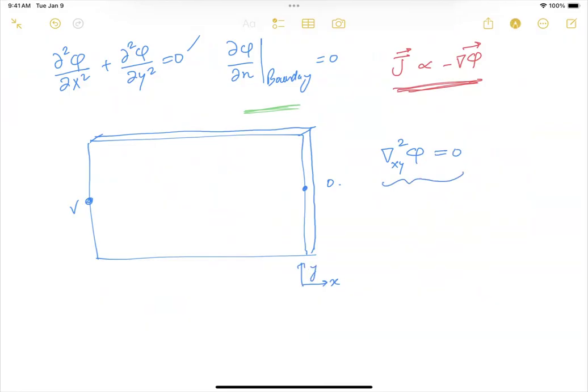And if you look at the form of this mathematical expression, it's very similar to what you would expect as the potential equation for when you have 2 point charges which are located in free space. So it is a good analogy to consider these two voltage taps, 1 and 2, as just being 2 point charges located in space. And therefore, the electric field E at, say, some cross section L over 2 is just going to be V over R, some distance R, where R is essentially this radial distance from this voltage tap.